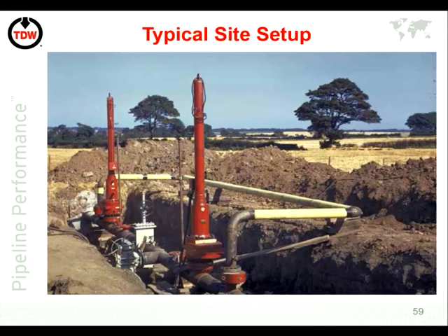Regarding the cutting operation, normally in a process plant, to do the cutting operation downstream of the pressurized pipeline, we actually need double block. Do we consider this as a double block? This one here is not double block, it's single block. And the reason it's single block is it's got one plugging head in there.